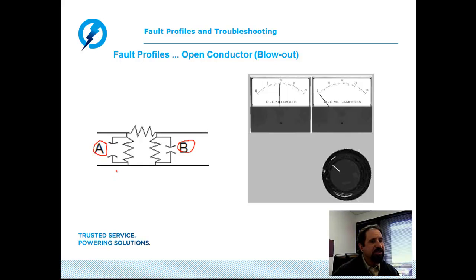And in some situations, this high fault current amperage traveling back will actually create what we call a burn back condition, where either the conductor burns back into the insulating material or the concentric neutral burns back. Bottom line, the physical distance between the remaining conductor and that concentric neutral has grown in size, leaving a rather large gap. Now, chances are the load side of the circuit did not see this high intensity of fault current traveling back on its neutral. So from the load side of the circuit, the gap may be much smaller and more reasonable.